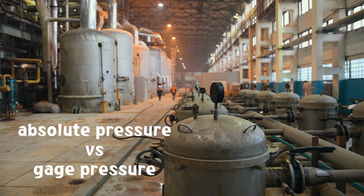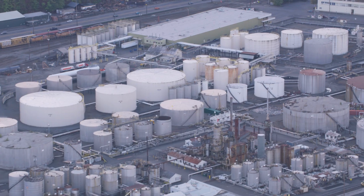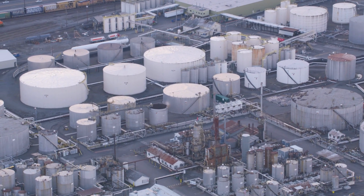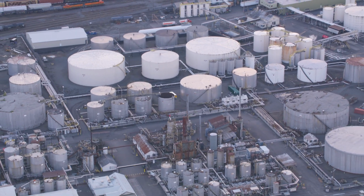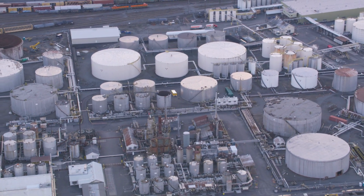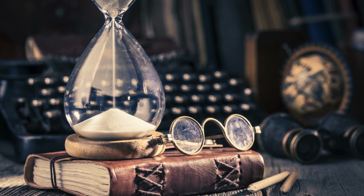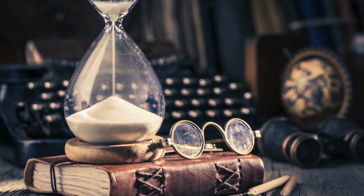What are the advantages of measuring absolute pressure versus gauge pressure? Since all the facilities in a refinery or manufacturing plant share the same elevation and atmospheric pressure, measuring gauge pressure is accurate enough for most processes. However, specialized situations call for absolute pressure, which are independent of fluctuations in atmospheric pressure.